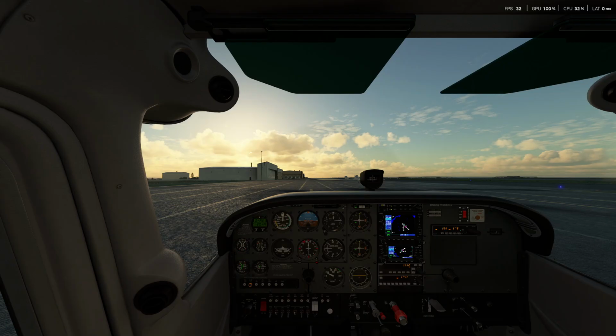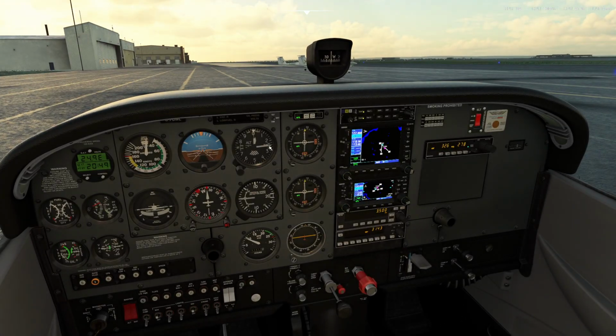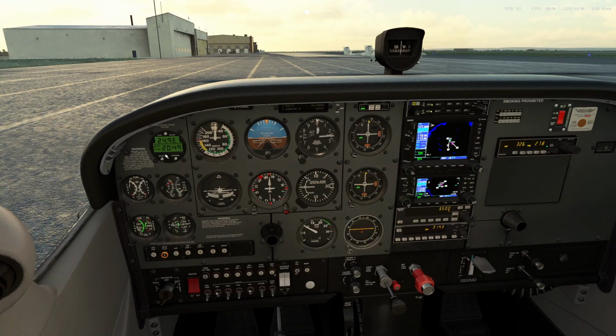And next one, ATC clearance as required. Again, ATC is not online, and we don't have simulated traffic because we're not flying on VATSIM right now, so I'm not going to simulate any radio procedure for this flight. And the last one here, altimeter, clock, and transponder. So the altimeter is set with 3017 for the altimeter. Clock is going to be incorrect because it's not actually.